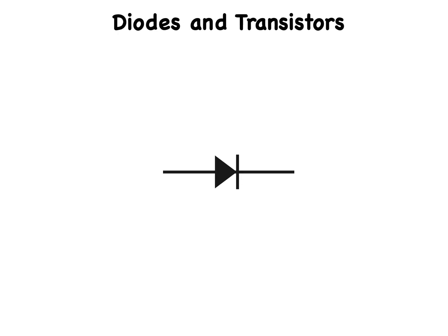This shows the basic symbol for a semiconductor diode. In this symbol, an arrow and a vertical line indicate parts of the diode, and the horizontal lines to the left and right indicate the leads. The symbol portrays a rectifier diode. The arrowed part of the symbol corresponds to the diode's anode, and the short, straight line at the arrow's tip corresponds to the cathode. Under normal operating conditions, a rectifier diode conducts when the electrons move against the arrow.